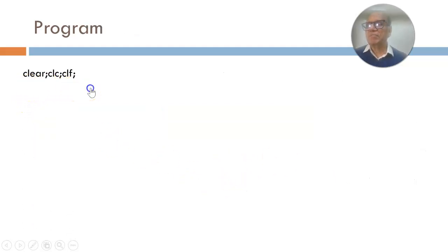So this is as usual. Then the cutoff frequency you would define. This could be something else. Of course, it will always have to be less than pi. In this case, we have said pi by 2, could be pi by 3, pi by 4, and so on. Then n1 is equal to 3. So we are going to use 7 coefficients, which means, because it goes from minus 3 to plus 3, remember? So minus 3, minus 2, minus 1, etc. So it will be 2 into n1 plus 1. That will be the number of coefficients. So n is 2 into n1 plus 1.